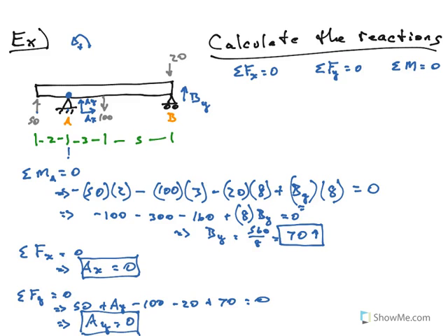If you're going through analyzing a system, if this were me at an engineering firm, I'd say, well, look, if this is how the system is, and it's going to remain this way, then theoretically, you don't have to spend any money with that pin. Just don't put the pin in, and it's going to remain in equilibrium by itself. You still need the roller, because the roller has a reaction, but the pin doesn't do a dang thing here. So pretty interesting. But this is how you solve reaction problems.